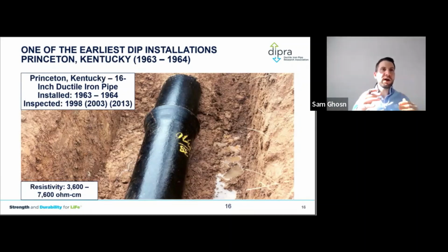Okay, low conductivity means high resistivity, means low corrosion current, and that means the electrolyte is not as aggressive for ductile iron in those areas. You bury that metal in that kind of soil, it will be there for centuries, no question.